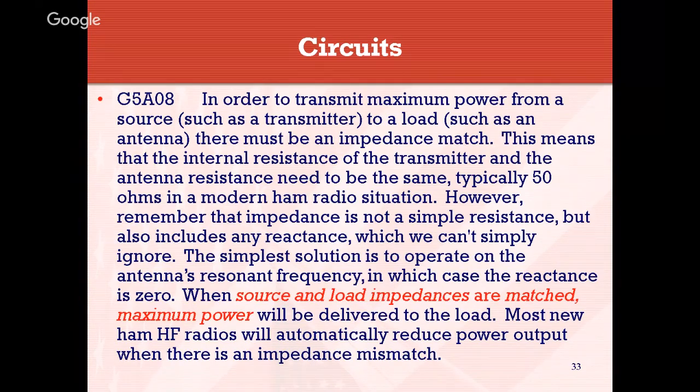You never ever really want to run anything greater than a 2-to-1 SWR on your transmitter, because anything over that usually indicates a fairly hefty impedance mismatch. To be on the safe side, operate under 2-to-1, even better, 1.5-to-1. You'll never get a perfect 1-to-1 match. You'll usually get a 1.1 or 1.2 for the central frequency that an antenna is cut to, or the resonant frequency of a tuned circuit.